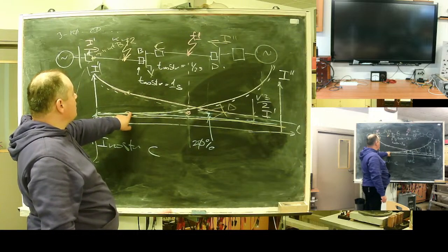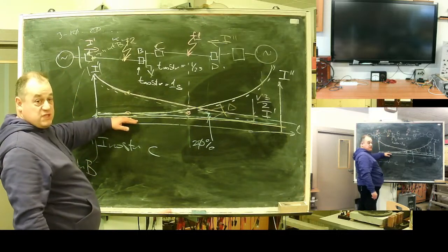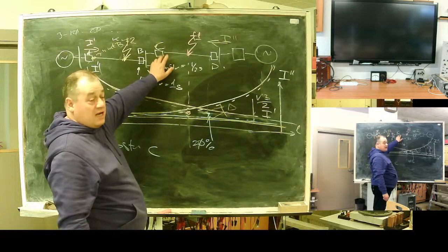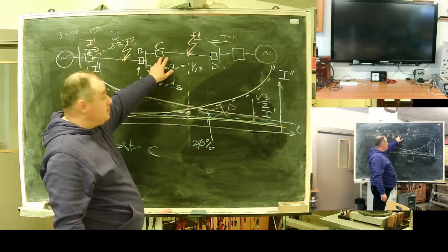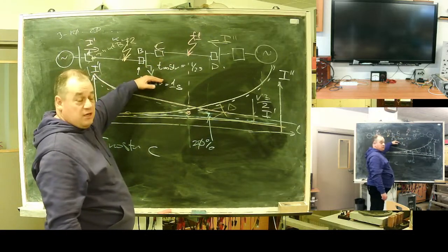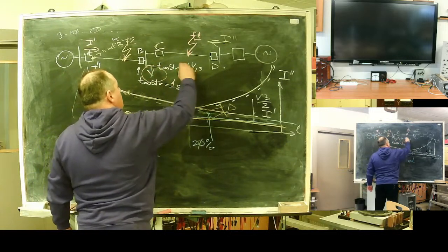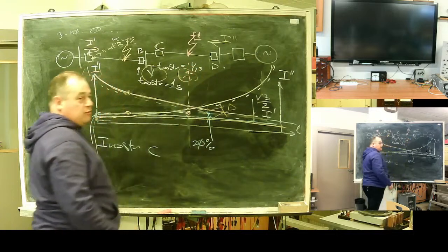It's a current that will flow through C and D. You can see both will start, and since here I have shorter time set, C will trip first. Again, killing this customer, unlucky. Here we will see an extremely angry and unlucky customer.